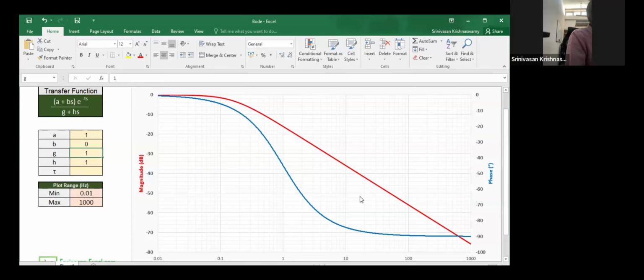Yeah, the smearing of sound would be more when you have feedback, because it pushes your frequency response lower. If you want to avoid that, you want to operate the device in its full frequency response. Then what you can do is add open loop filters at the output that compensate for the nonlinearity of the system. Tuning those filters is slightly problematic. Tuning those filters typically needs more advanced math, and the thing that people normally use is AI or ML based methods in order to tune those filters.